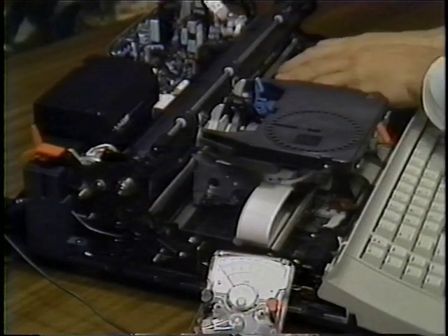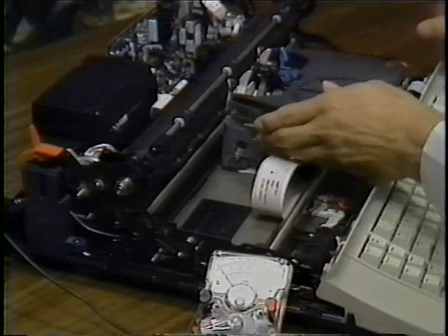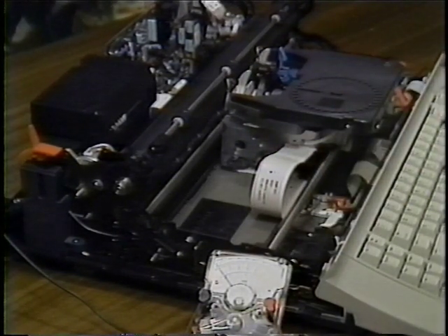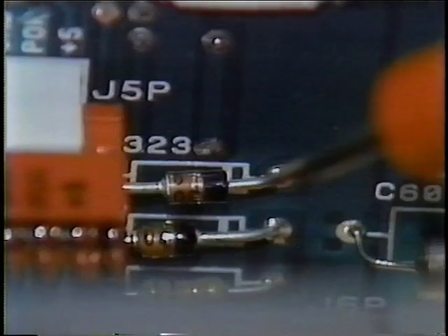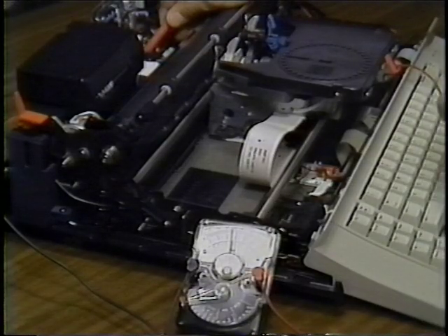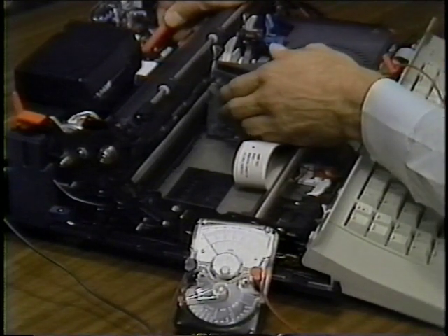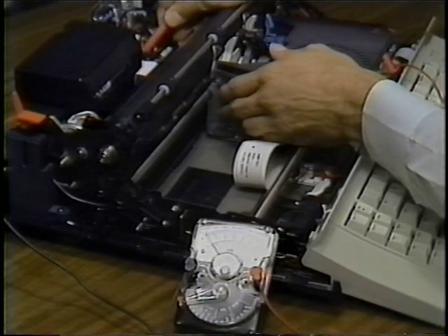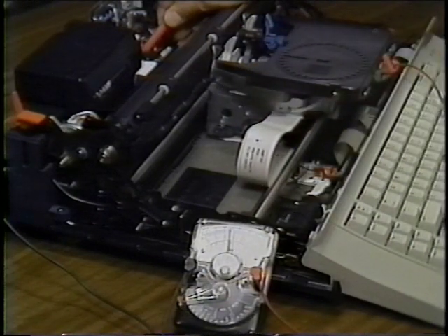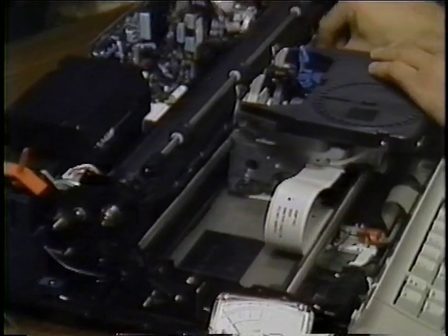and remove the transport belt to prevent the carrier from moving. With the meter set on the 12-volt DC scale, place the VOM meter lead on the sense pad on the printer board. When the homing sensor is not blocked, the meter should read from 3 to 5 volts DC. Press the homing flag in slowly. When the flag blocks the homing sensor, the meter should read from 0 to 1 volt DC. Turn the machine off, and reinstall the transport belt.